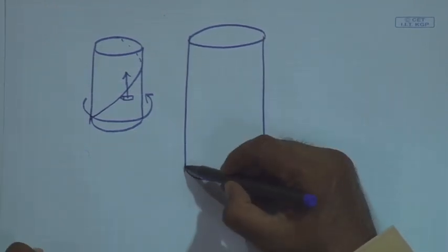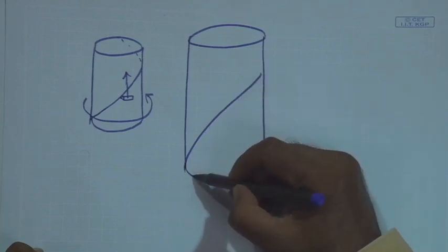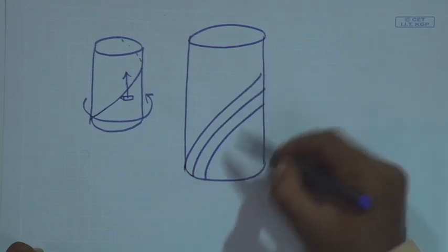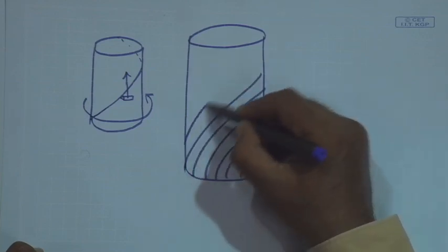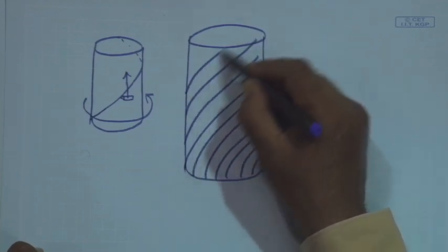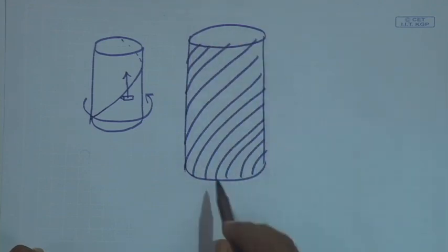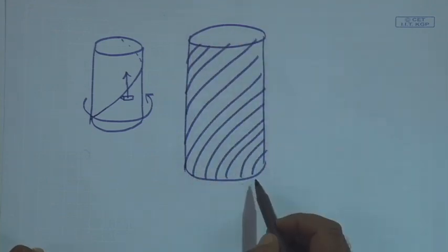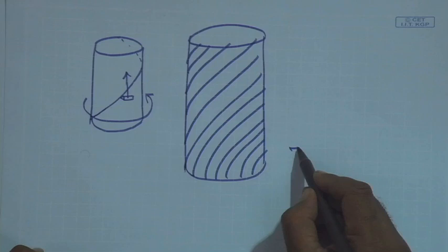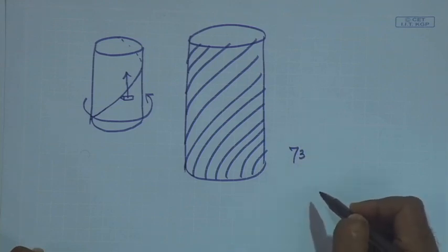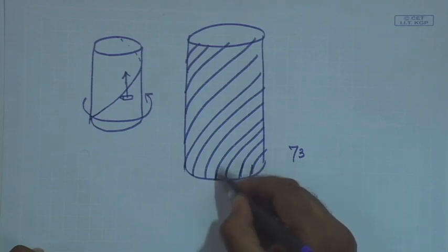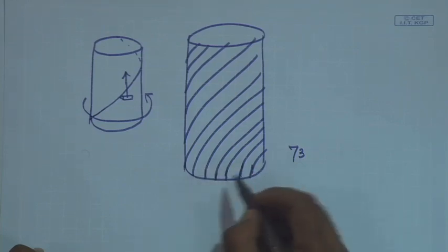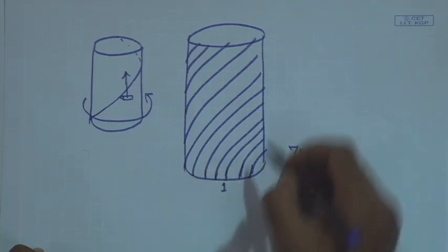So, in a gear you definitely have multiple starts, because you have so many teeth. These are the helices, and they belong to different helices. They are multiple starts. How many starts does this particular threaded element have? If you are cutting 73 teeth, it has 73 starts.